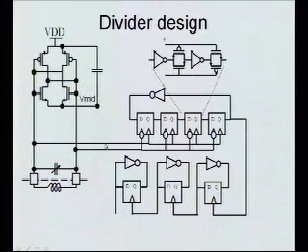Okay, so these 2 lines here are connected to these 2 lines here. So this looks like a capacitor, and there's an inductor across it. And so it resonates. So what that means is, if it's pure digital, every time you charge up a capacitor, that's dissipative, right? You're charging it through a resistor, in effect. Now when I'm charging it with an inductor, a lot of the charge, instead of being dissipated, actually flows back through the inductor. And so I get a step up of Q.